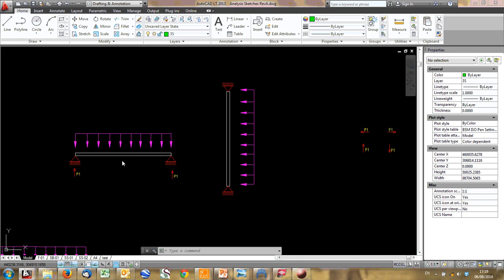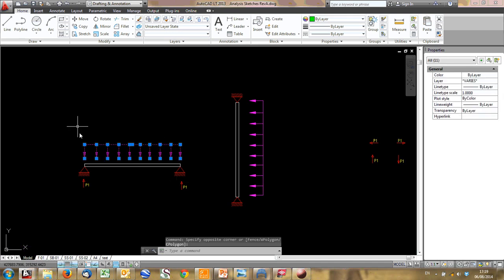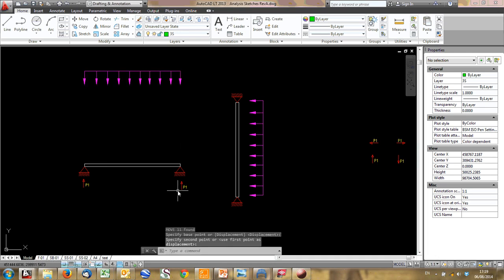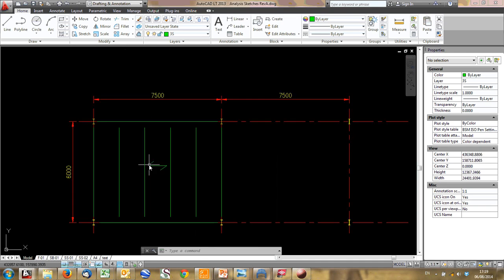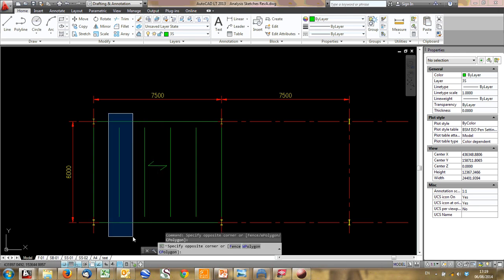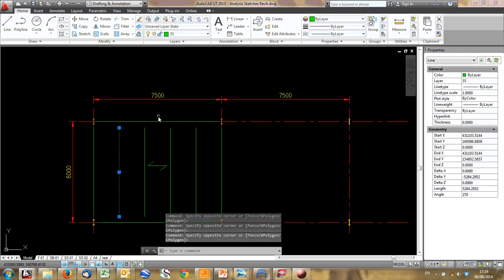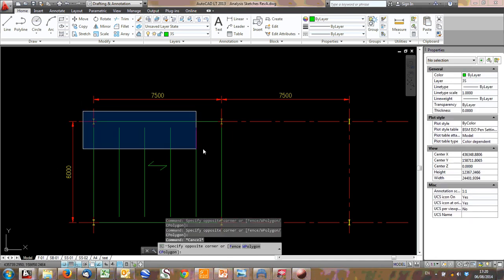and then we do the exact same thing. We get our reactions, and then we go to the next beam, and we put this reaction on top, and we might have two or three beams, and do it that way. For instance, let's say this is a panel that shows that it's a one-way spanning slab, not a two-way. That means all the load, if I was designing this beam, the load area would be that. I can get a UDL, design the beam, design this beam, etc. Will that all be the same? And then those will put reactions onto that.